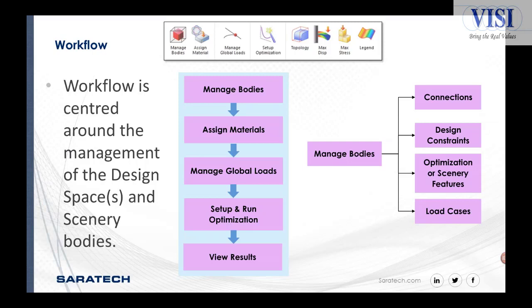So after you get your body all set up, you specify your material. If you have global loads, accelerations, type like that, then we set up and we run our optimization, and then we can go ahead and look at our results.